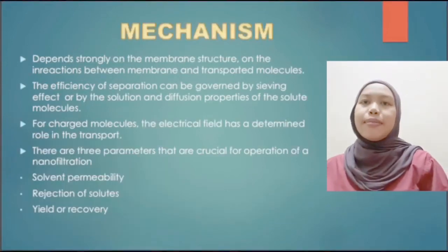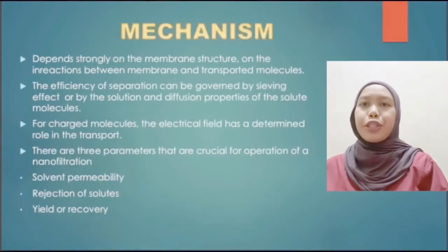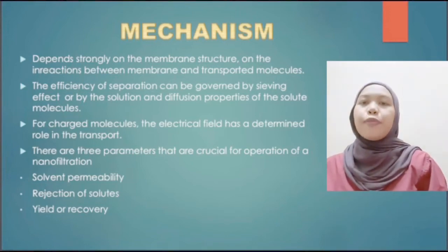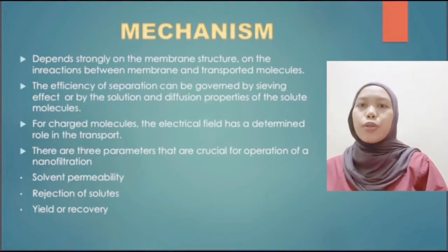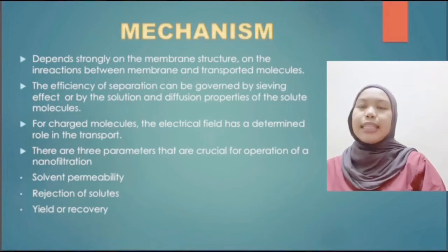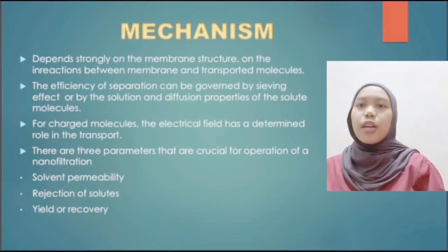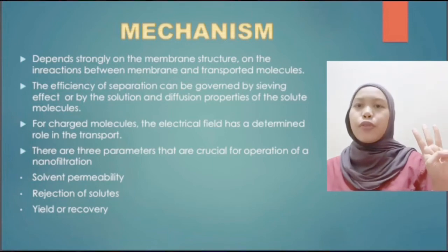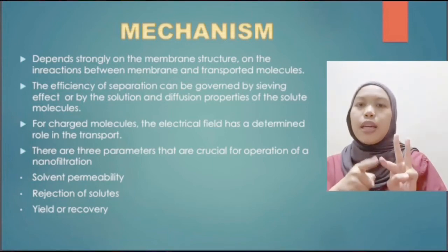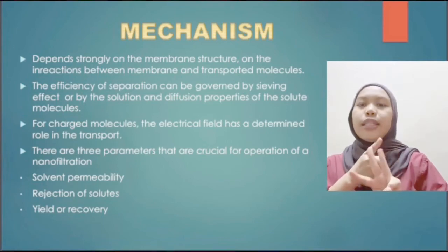The mechanism depends strongly on the membrane structure and on the interaction between the membrane and the transported molecule. Efficiency of separation can be governed by the sieving effect or by the solution and diffusion properties of the solute molecule. For charged molecules, the electrical field has a determined role in the transport. There are three parameters that are crucial for operation of nanofiltration. First is solvent permeability, then rejection of solute, and yield or recovery.